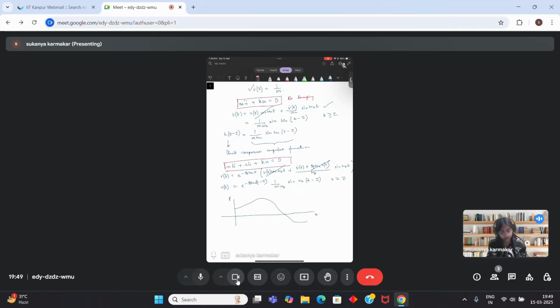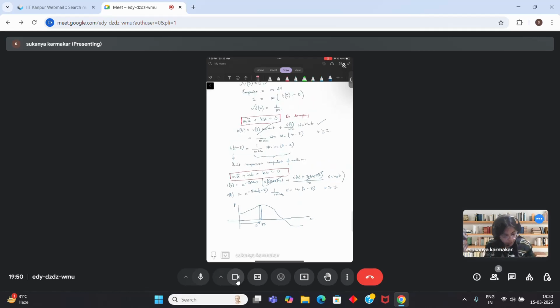So t with respect to time. And what you have just written here is the result due to an impulse at time t, where you are taking this value as d tau. So you have the value for this one impulse. If you can add the results because of all these small impulses, suppose I divide the force into small parts, that will be the response of my single degree of freedom system to this arbitrary force.